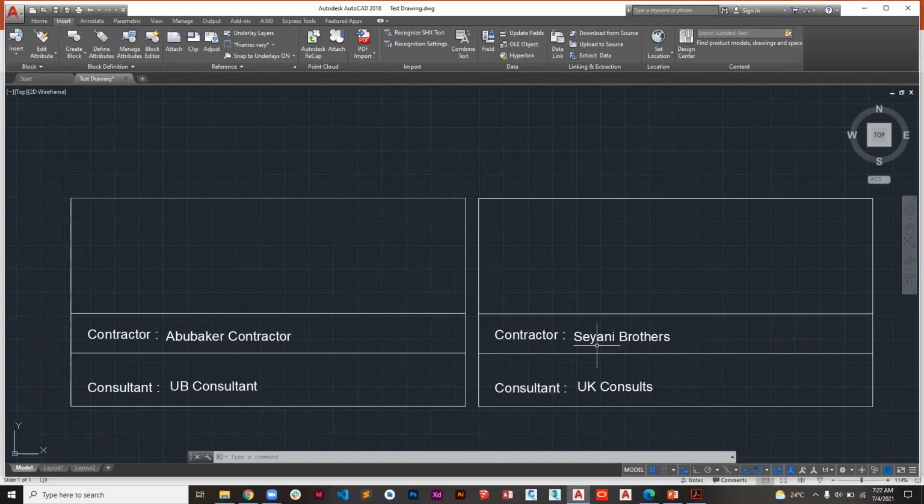But I think you can mostly use it on a title block where there are different values. For example, maybe you are coming up with a bar bending schedule, or a windows and door schedule on the sides where you have dynamic inputs, or you have varying units. That's where you can use it, so that you just insert a block, then you enter length, width, height, like that.